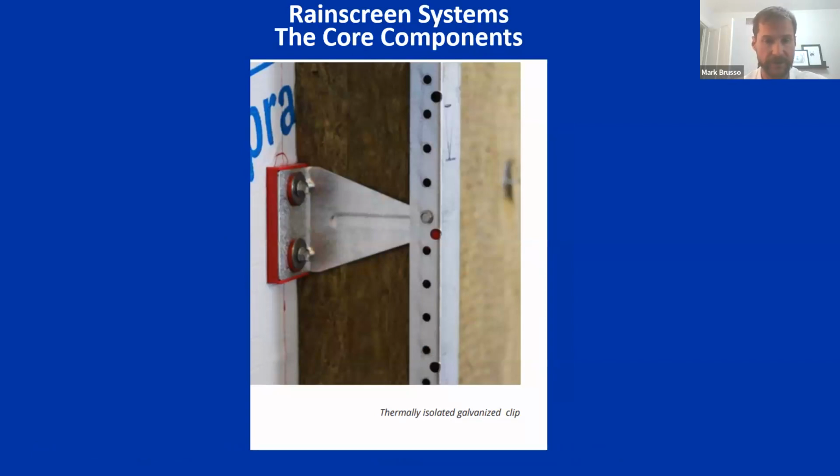Then we are introducing a clip and a girt, or a clip and channel system, which can be thermally broken. That's an image of a Fabrica shim, which is a thermally isolated shim. There is a method of fastening this bracket system. And then the cavity can be one of a couple of different types of insulation. And then there will be an exterior cladding as part of that.